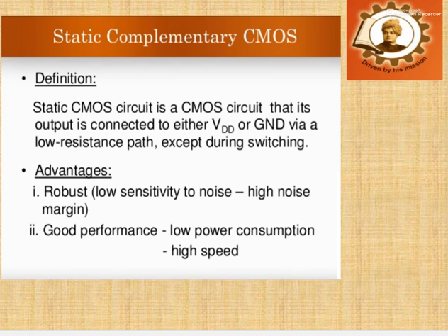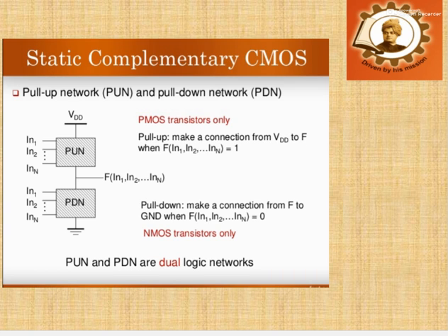In a CMOS logic gate, there is an array of pull up transistors and an array of pull down transistors. Here the pull up and pull down networks are operated by input voltages in a complementary fashion. When the pull down network conducts for an input combination, the output node establishes a low resistance path with the ground, resulting in a zero output. When the pull up network conducts, the output node establishes a low resistance path with VDD, resulting in a logic 1 as output.